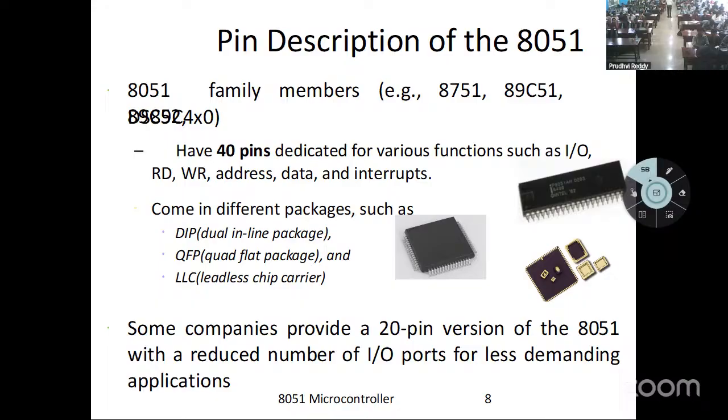Next, there is one more package. It is not required for you, but I am sharing it for understanding and knowledge. If you divide the 40 pins as 20 and 20, the size increases vertically. Instead, if you arrange 10, 10, 10, 10 on 4 sides, then the size becomes half.